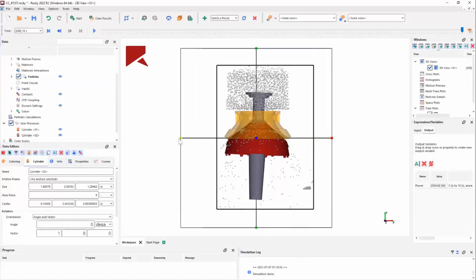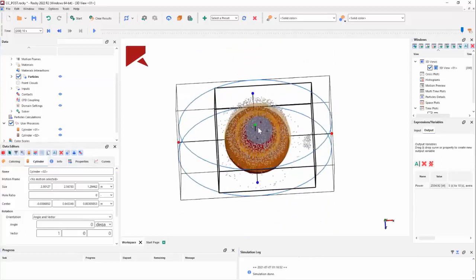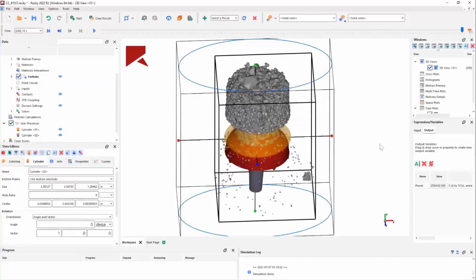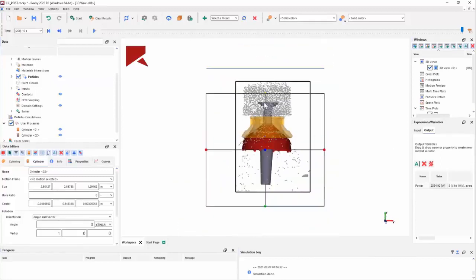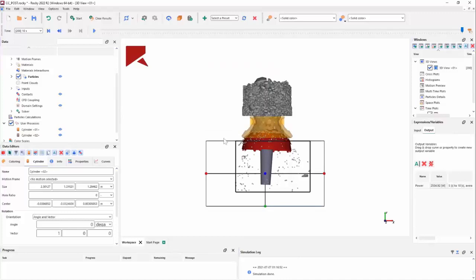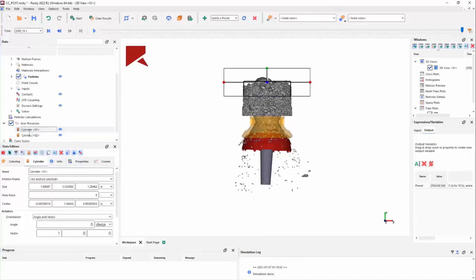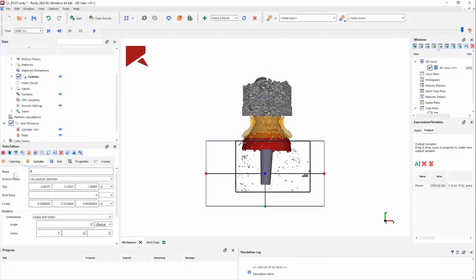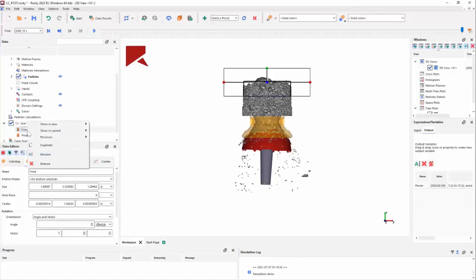As we can see, the particles are leaving the domain, but we have a very nice tool in Rocky that allows us to virtually compute properties of all the particles that cross this region throughout the simulation. So I don't need to store and collect all those particles. I will rename here just for cleanness of my post-processing, and now use the so-called particle time selection.